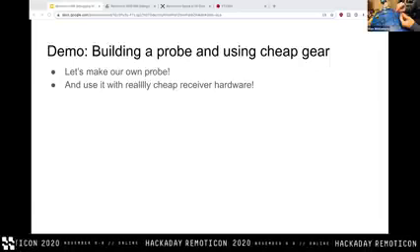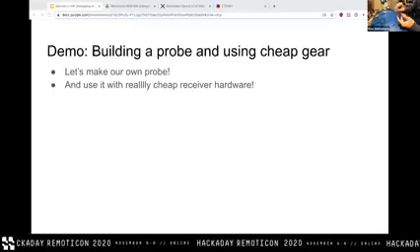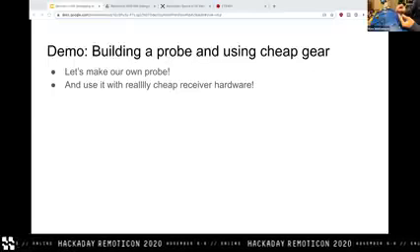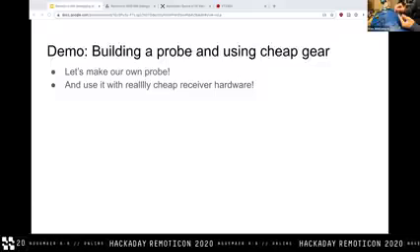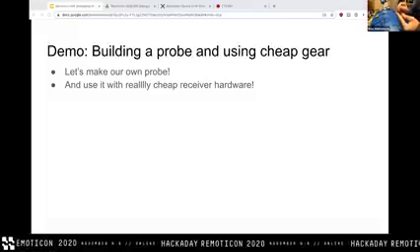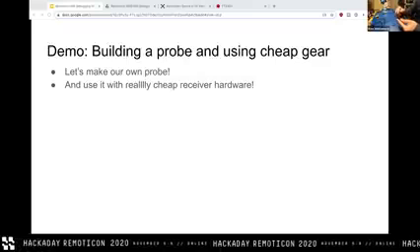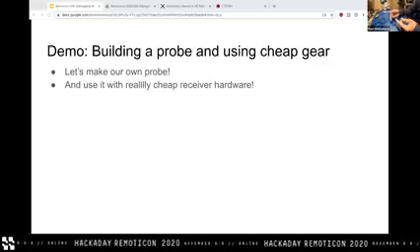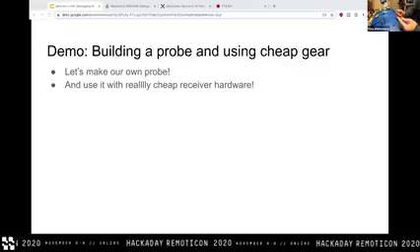If we look down here, the probe theoretically should be insensitive to any magnetic field in this region because, one, the induced voltage is proportional to loop area. The loop area is really tiny on any of these individual little twists. And also they alternate direction each time. So it's effectively if you wound a transformer one way for one turn and then the other way for the next turn and then the other way for the next turn and so on, so that basically every turn just canceled itself out and the net output of the transformer is 0.